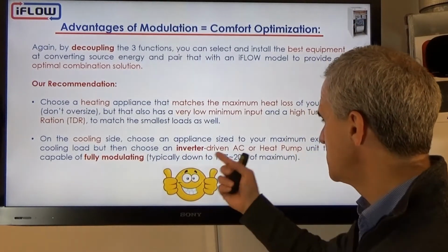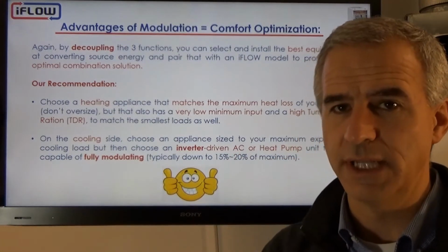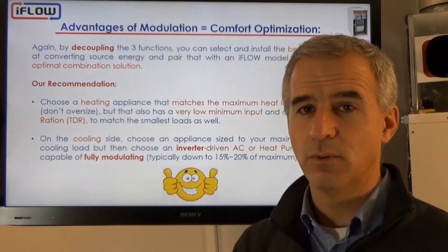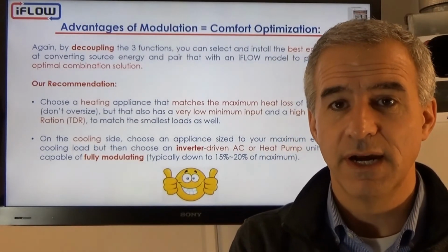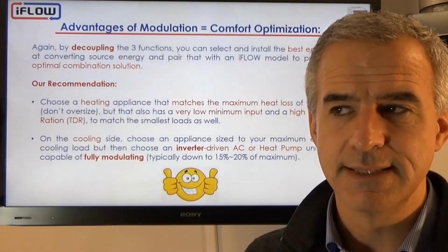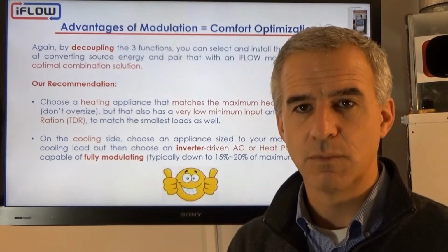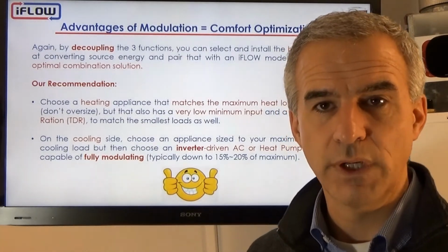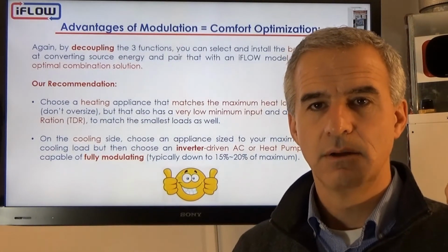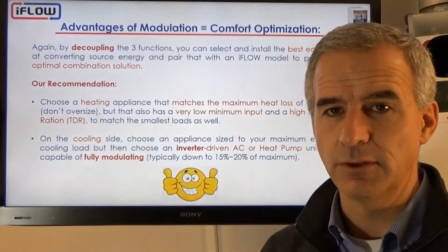So an inverter driven system, whether it's an AC unit or heat pump, will be fully modulating. And then we take that modulation capability on the AC side, pair it with our modulation capability on the iFLOW side, and we can deliver. So if we have one zone that only needs 150 CFM, a very, very small load, we can do that. You know, let's say 4,000, 5,000 BTUs in a certain area. We can deliver that with an inverter and with the iFLOW.